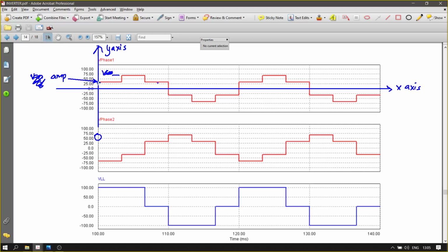Go back and find what the amplitude is for that, right? And the rest is similar to the derivation just now. If you look at that, this is odd and quarter wave. Therefore, an equals 0 for all n, and bn is 0 for even harmonics, even n.